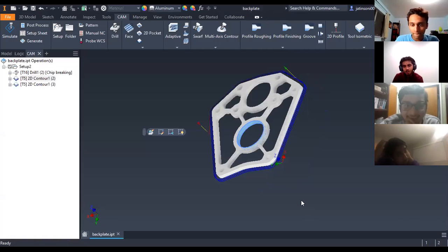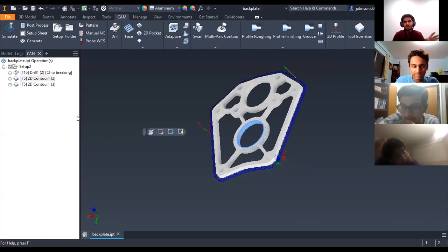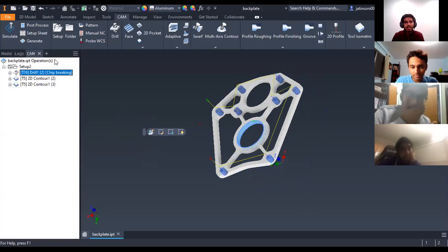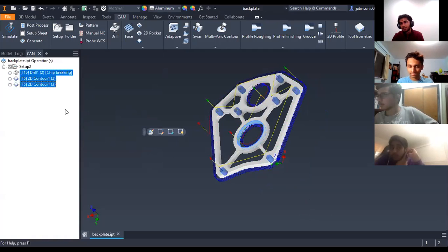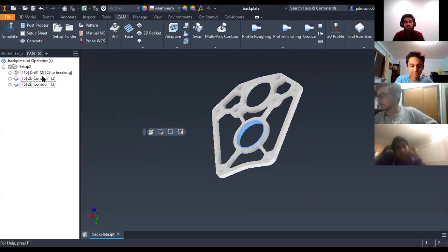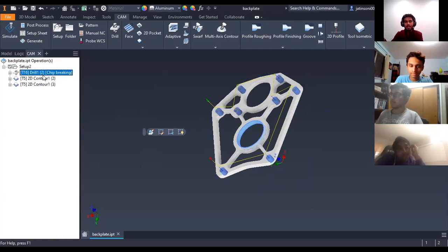Right. So with the 4 minutes we have left, the final process for actually being able to put this part on the CNC would be you select it and you do post-process. That's the compiling portion, right? Remember that we have to drill and we have to put screws in, right, if we're on a CNC. So you don't want to select all three at once, because all the G code will be right next to each other. The moment it stops drilling, it would go straight into making the pockets, which is not good. So we just process the drillings all by themselves.